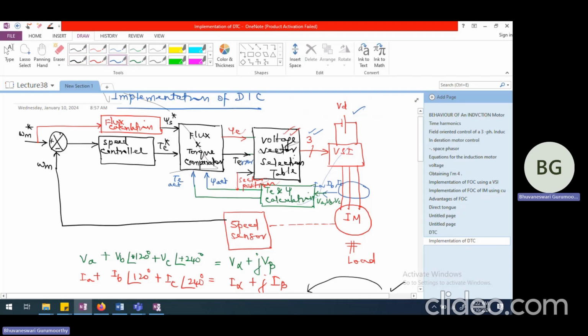So the direct torque control major plus point in this particular case is we are directly looking at voltage vector selection from a lookup table, and all we are doing is only sensing voltages and currents. In fact, voltage sensing is also not essential because we have the switch positions from which we should be able to get the voltage calculated.